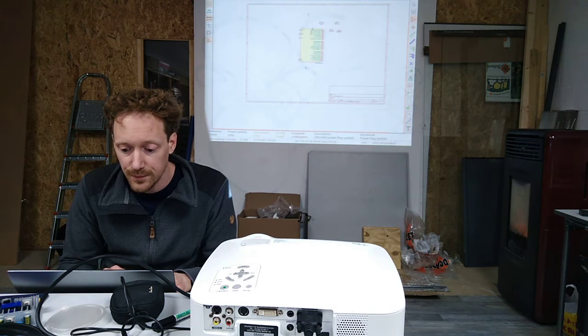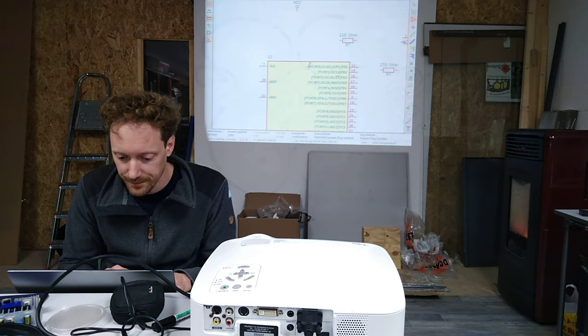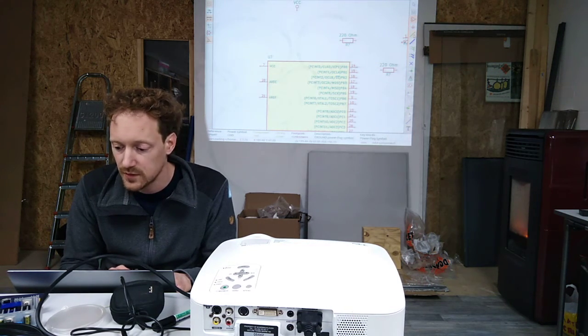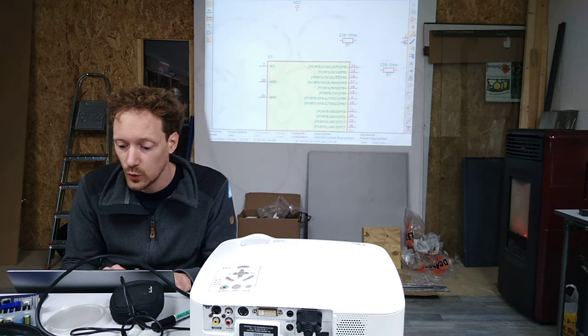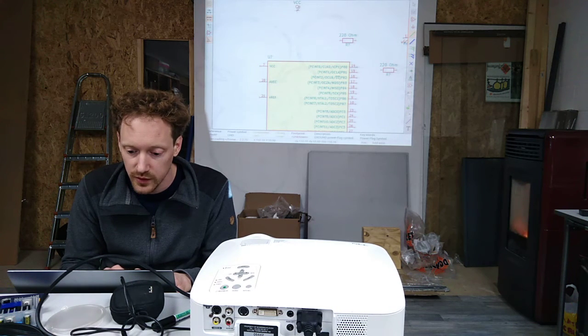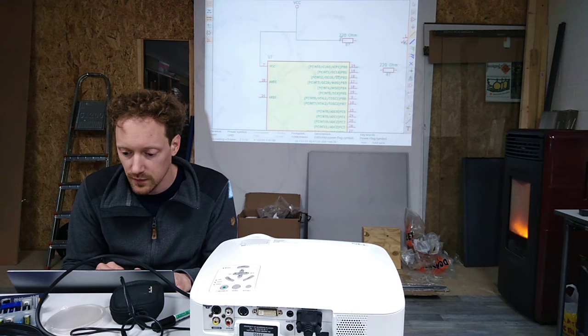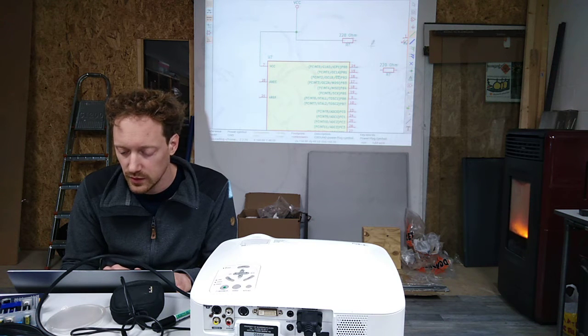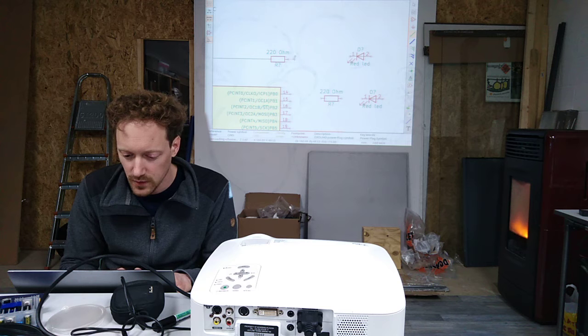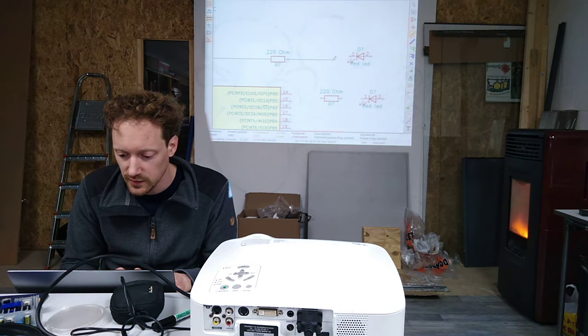So now we can basically build a circuit, by picking the wire tool, and now we're going to connect the VCC of the board with the VCC that we just arranged, and then we can add it to the resistor, and then we can connect it.